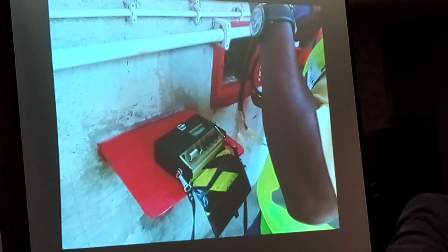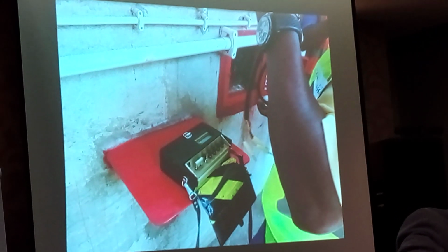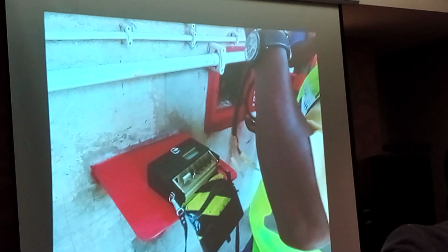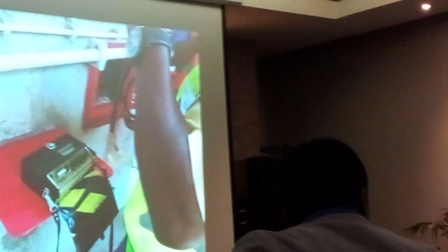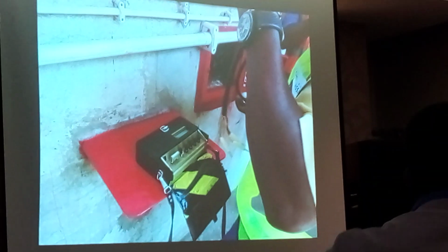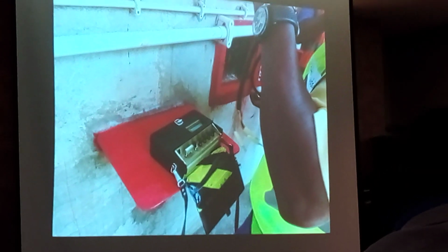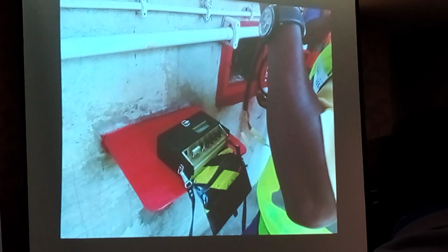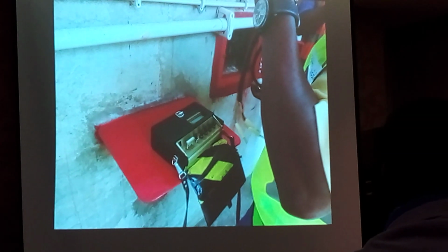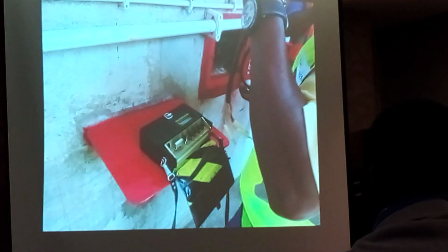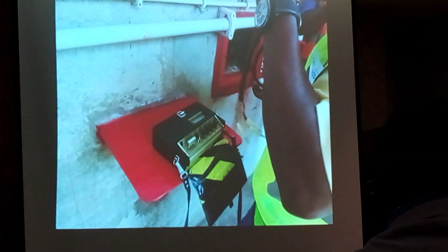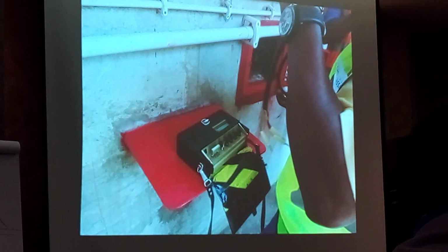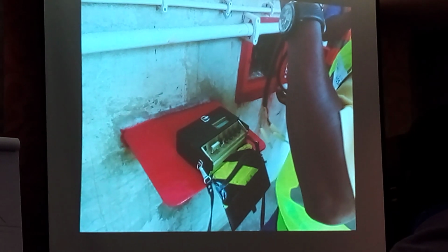Most dams, the instrument is there somewhere. The person that needs to take the reading must go on their knees or sit down on the ground. Are you going to get good measurements if the person has to sit on the ground every time? No. So please make provision for an installation where you can put your readout unit there. I know it's a small increase in your cost, but over the long term you will get very good monitoring results.